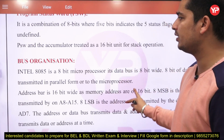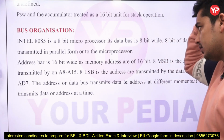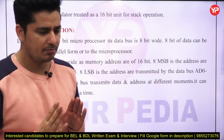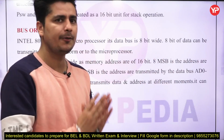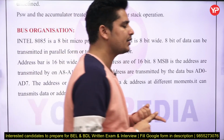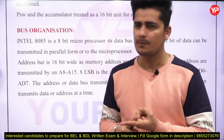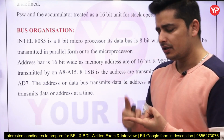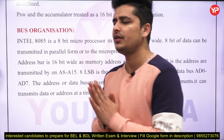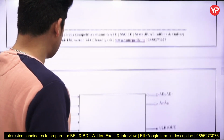Now the bus organization of 8085. If I'm talking about the bus organization, what is the work of your bus? Bus means which is carrying the information, right? Basically there are two types of bus. One is address bus, another one is data bus. Inside your 8085 we have a data bus of 8 bit and an address bus of 16 bit.